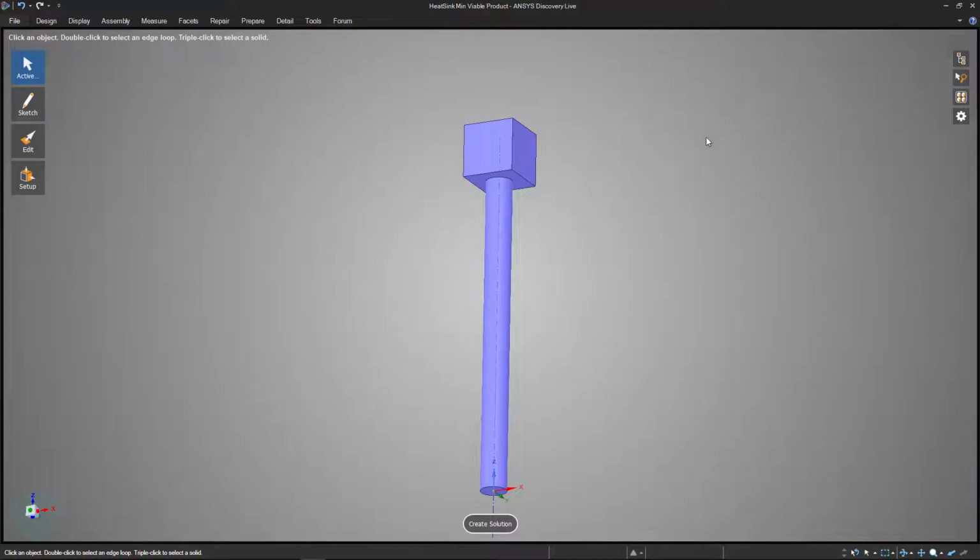That'll be useful. For our solution here, our thermal analysis, we're going to apply heat to this bottom rod, similar to boiling water, because this will be the part inside our hot cup of coffee or our hot drink. And then we'll look at how heat is transferred to the environment from the top part here, mainly through convection. So let's begin by creating our solution. The options here, the left-hand one by default, is the thermal behavior, so that's the one we want to keep on.